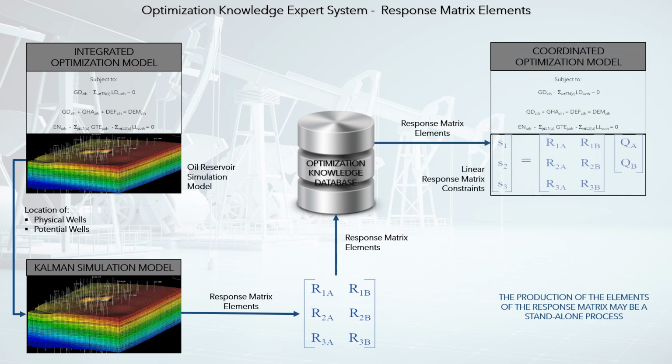Then, the elements of the response matrix will be used by the coordinated optimization model when the optimization process requires this information. If large-scale optimization methodologies are used, it is possible to establish a dialogue between the information system and the optimization model as the optimization process progresses, decreasing the dimensionality of mathematical problems and speeding up solution times. It should not be forgotten that the cases in the real world are complex and of high dimensionality. For example, it is quite possible that it will be necessary to coordinate simulation models of multiple reservoirs.